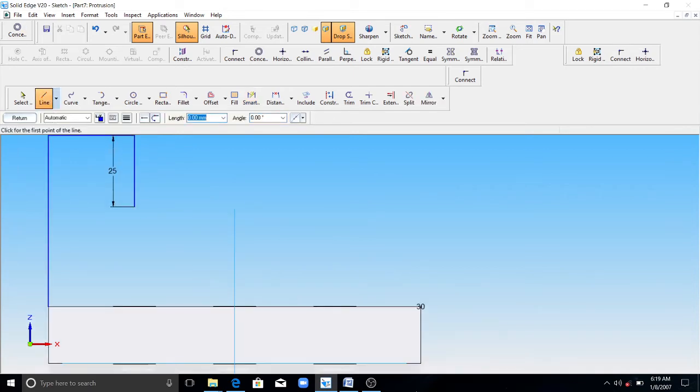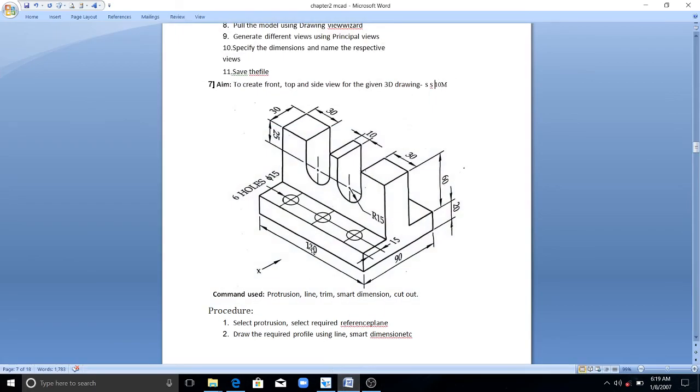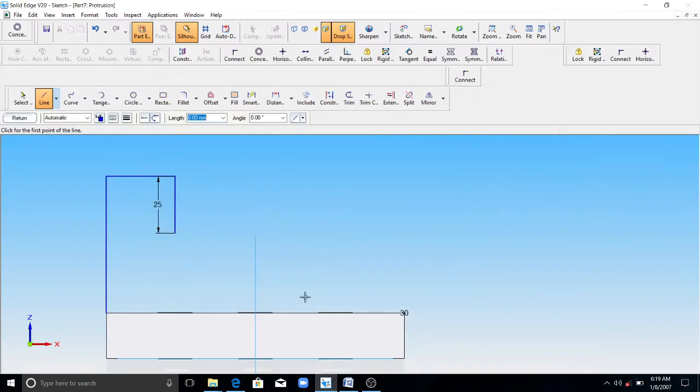So that you have a radius of 15 here. If this radius is 15, it means the diameter is 30 here. That means this distance is also 30. So the center of this one, from here to here, is 15. You need a center to draw the semicircle. So I'll draw a center here, 15 mm from this edge.